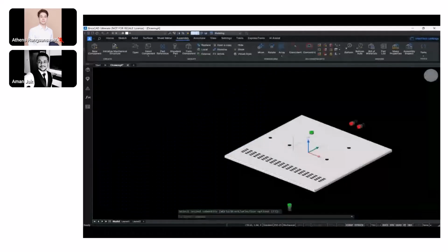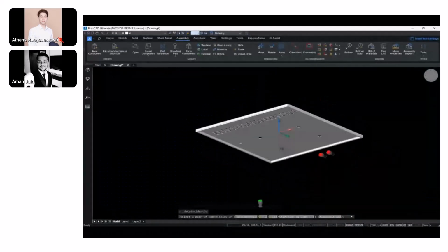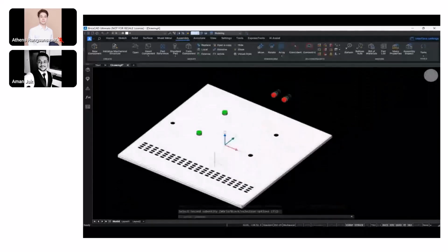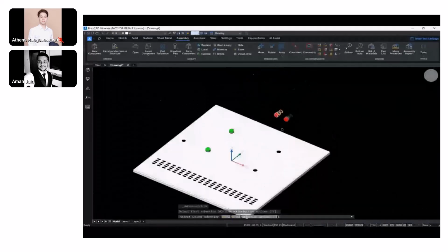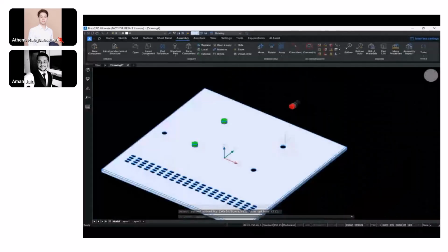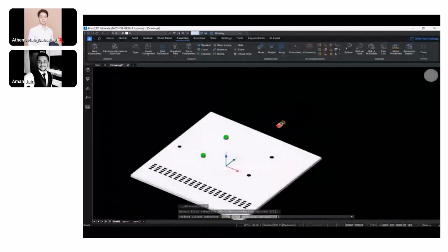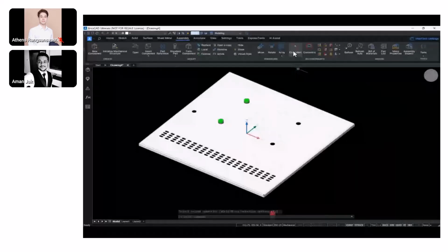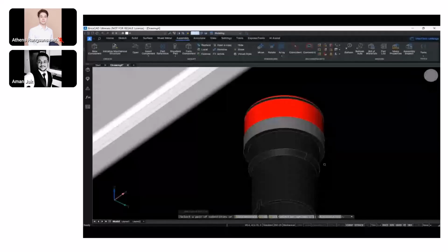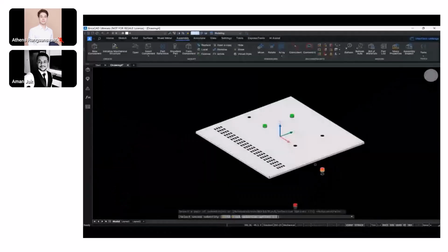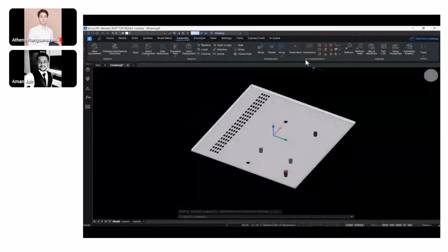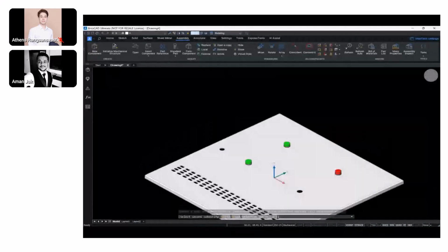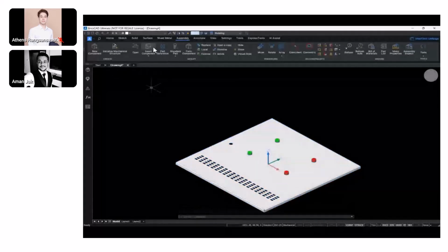One thing that I can do is copy the same switch that I had constrained earlier. Just copy it and place it onto the next hole representation. That would have done things for me. But then this is how I can make sure that the constraints that I've applied are kind of perfect. And then in case I want to change the constraints in the near future, or if the whole geometry shifts, the entire geometry along with the switches needs to shift as well. So if there's a change in the design principles, let's say if the hole has to shift by another 10 mm or so, all I need to do is just shift the hole by another distance of 10 mm, and the entire geometry would update automatically, right? So instead of copying it at that particular place, constraining the geometry is really handy. And as you can see, it's really very simple in terms of how to apply constraints: coincident, concentric, distance, and there are other constraints as well, which help us complete our assembly modeling.